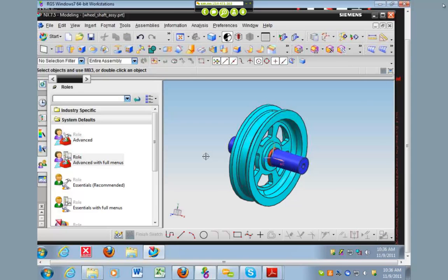The other option is called gluing. That one, you don't have to have the parts actually touching. They have to be pretty close, but your meshes don't have to line up. It's an option that essentially makes lots of little connections from node to node, even if they're separated or skewed a little bit. That will pass stress from one part into the other part. Eric will show you what the button looks like in the tutorial. That one is nice because essentially you don't have any discontinuities in stress from one part to the other.